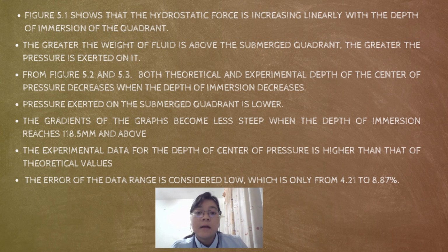It is logical that the hydrostatic force increases when the pressure exerted increases, as force is directly proportional to the pressure. From figures 5.2 and 5.3, it can be observed that both the theoretical and experimental depth of the center of pressure decrease when the depth of immersion decreases. The lower the depth of immersion, the less fluid is above the submerged quadrant. Thus, the pressure exerted on the submerged quadrant is lower.